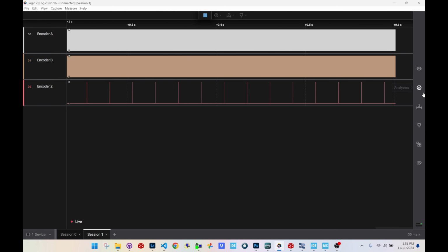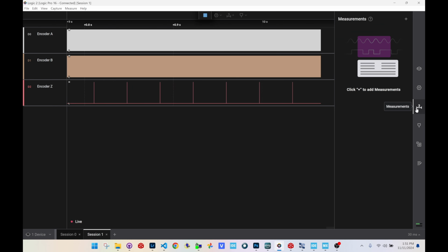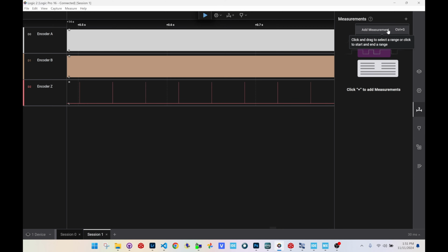When the motor is spinning slow, this time is long. When the motor is spinning fast, this time is short. This is how I'm calculating the RPM of the motor. This is an easy method to drive a brushless DC motor. It gets more complicated whenever the motor is sensorless and whenever you use FOC in order to calculate the ideal waveform.